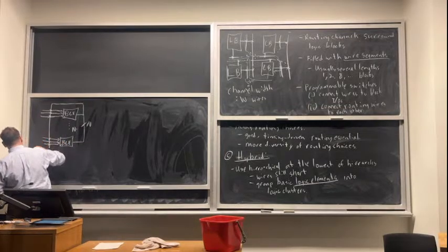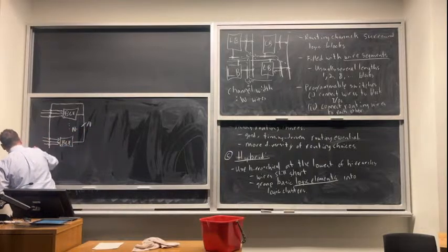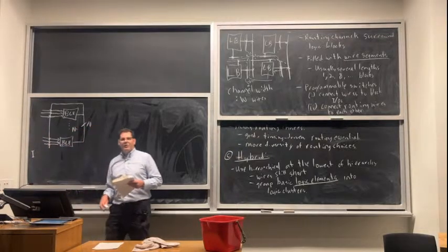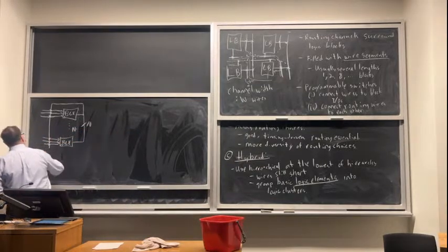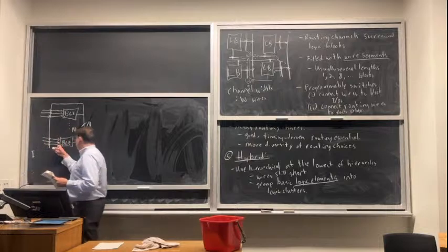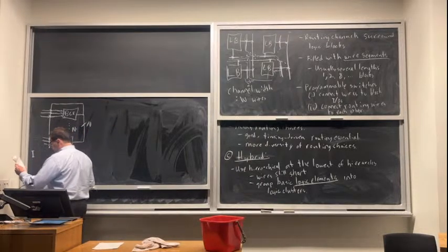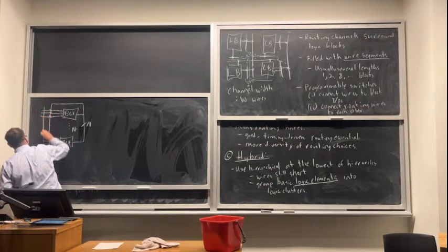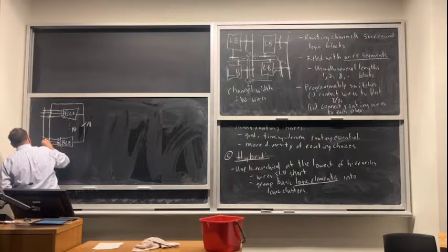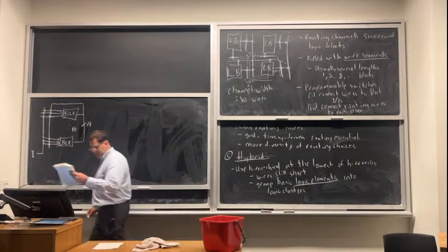There are also some signals that are going to come in from the programmable routing. Okay, so we have some number of signals, say I, that we can get in. And instead of connecting straight to the inputs of these basic logic elements, we have those drive some wires that can connect to the various inputs of these BLEs with programmable switches.